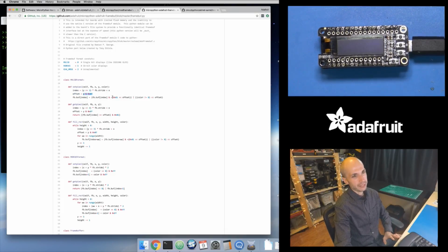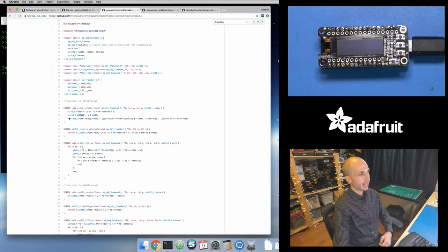Now in most cases this doesn't really matter because a number is a number, and if you're just doing simple operations like addition, subtraction, division, you don't really care. But sometimes you do care, because when you get to the limits, in the C code this is an 8-bit value. So if you have a value like 254 and you add 2 to that, it's going to overflow.